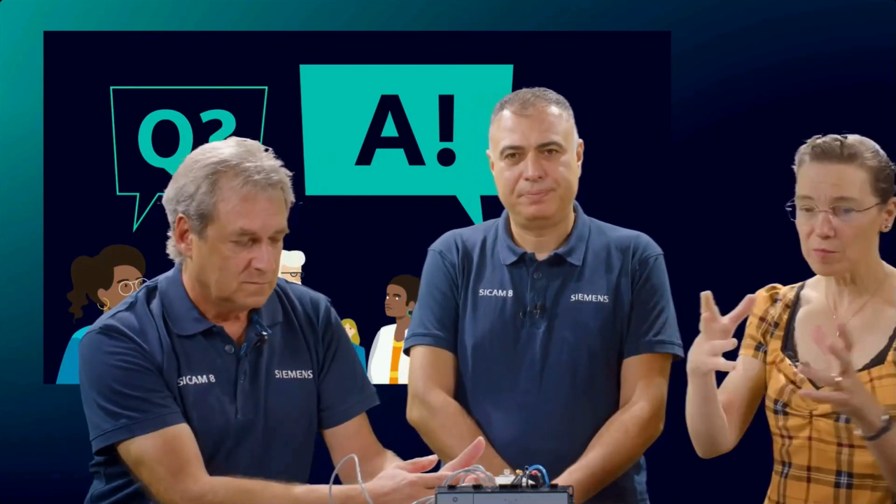I remember customers started putting things here and there, and a lot of hardware, and then it's all in one responsible. I have just to mention that this is not a standard RTU. Okay, we have all functionalities of the RTU, but the device itself is designed for medium voltage, low voltage distribution substations, and especially for the acquisition of the low voltage bus bar or the transformer output.